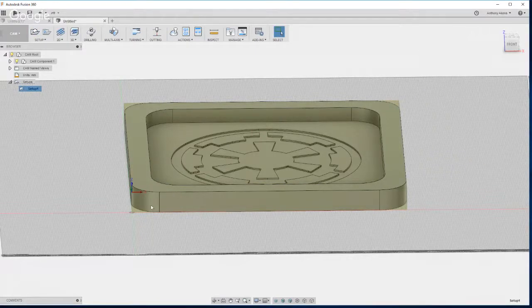It's important that the values you enter actually match the size of the wood that you got. So don't trust the store, actually measure it and type it in. Once you've set your stock size, your setup is really done. Now we can start doing the CAM.